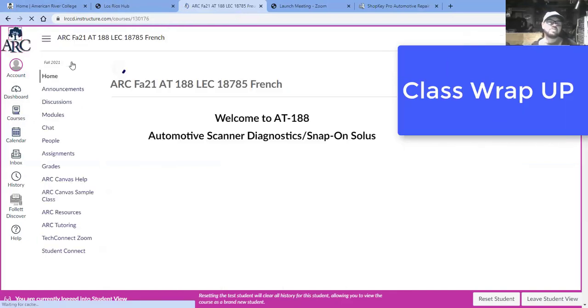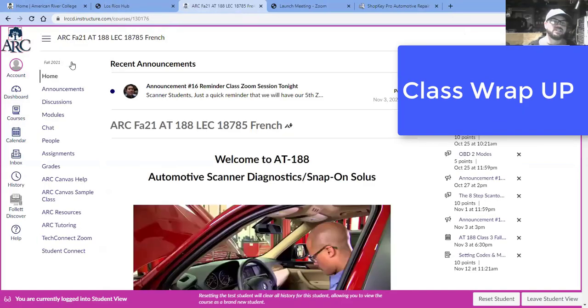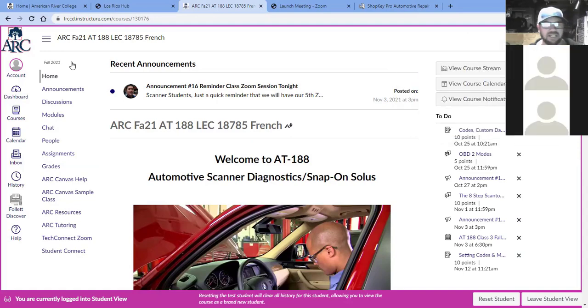And that's really what I wanted to cover today. I just really wanted to teach you guys about fuel trim and how important it is to leverage that because it can help you establish a condition. And that's a big thing to do. I want to know, is the engine running rich or is it running lean? If I have any type of engine drivability problem, whether it's a lack of power, a stalling issue, a surging, is it running rich or is it running lean can really give me a good direction to go as far as my diagnosis, and fuel trim is a great way to get there.